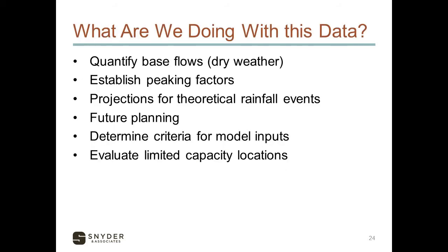So what are we trying to do with this data? Trying to quantify base flows for our dry weather periods, establish our peaking factors, how much I&I is in our system, project out theoretical rainfall events to understand capacity limitations, future planning, if we want to expand to handle a larger frequency event, maybe understand some of the I&I reduction that we get from pre and post flow monitoring from rehabilitation, determine our criteria for model inputs, and evaluate limited capacity locations.